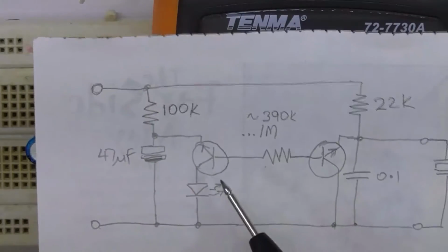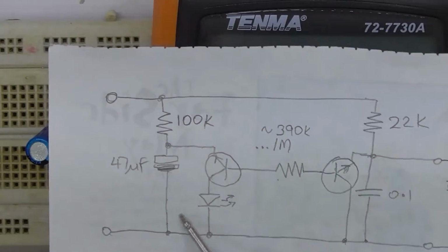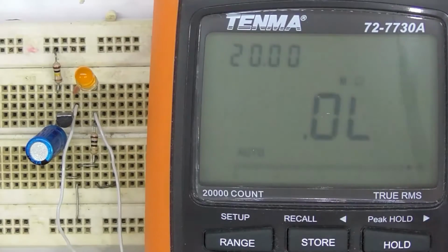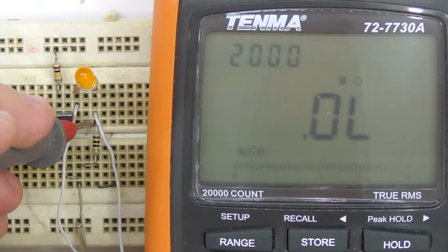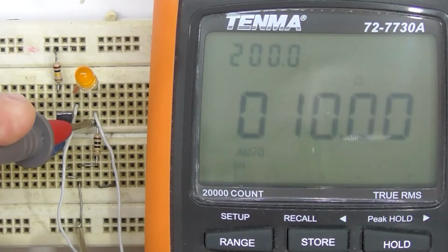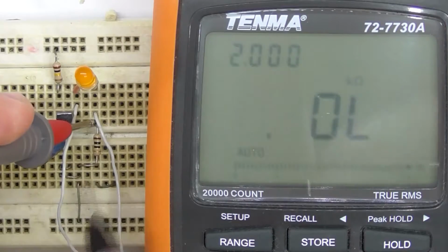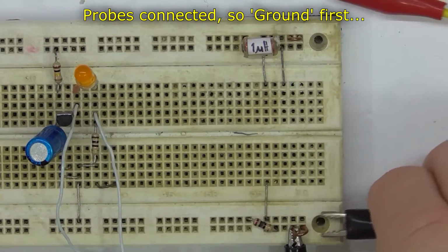So in essence, I've put a 10 ohm resistor in the cathode, and I've set up the oscilloscope with channel 1 on the anode and channel 2 on the cathode. The only thing we might need to know is the actual resistance of that 5% resistor, so I just measure between the ground and the resistor, and we get 10 ohms exactly. Yeah, it's a 5%, it's a gold band. So, how do you like that? Anyway, let's apply power and we'll look at the results.